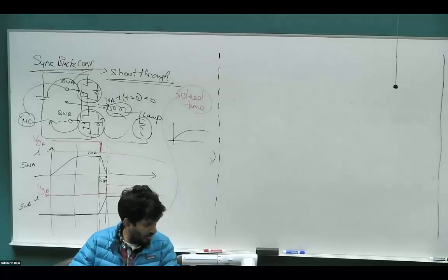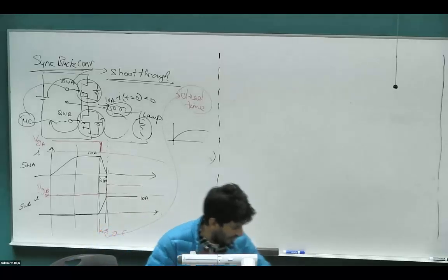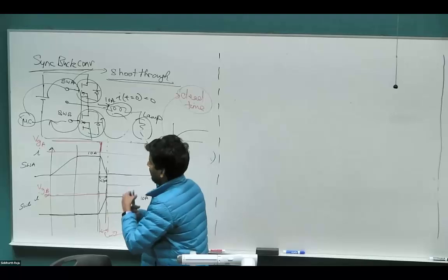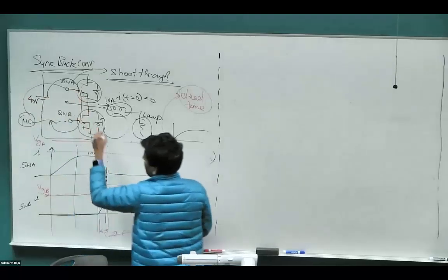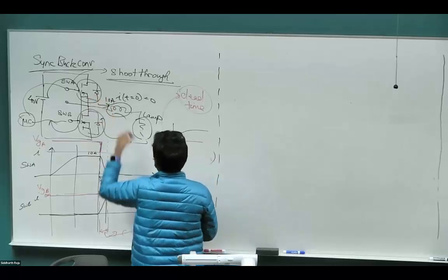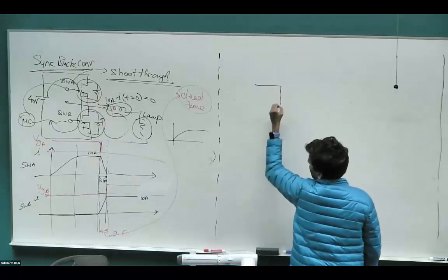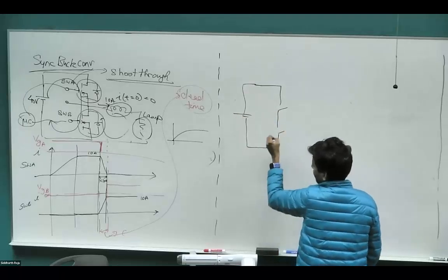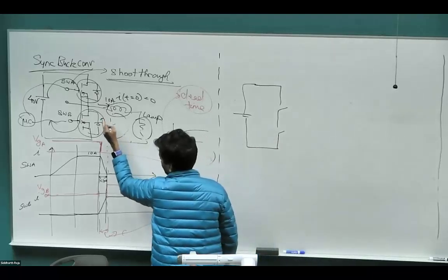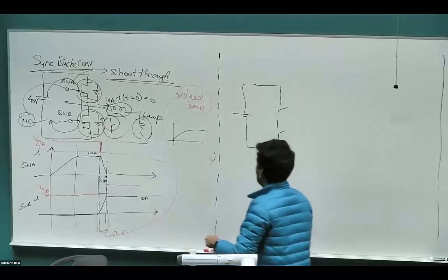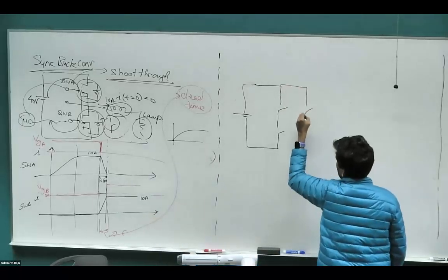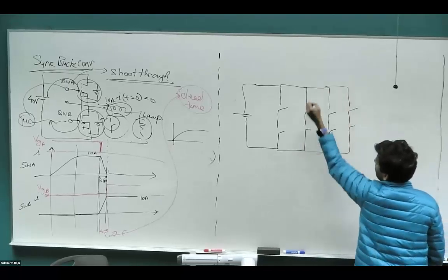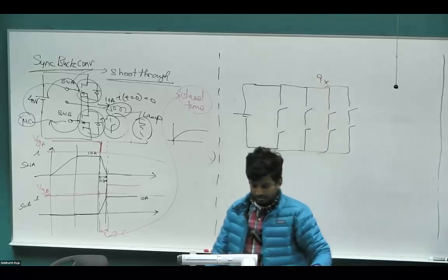Okay, so on the table again, I have the power supply, I have that black box. So now we know exactly what's inside the black box. It's basically just this DC bus voltage, which is 40 volts, connected to these two switches. And I can keep on adding more and more of these. Right now, we looked at only one. So instead of that switch, let me draw it like this, just to make it simple. Going forward, I'm going to use this symbol, which means this whole MOSFET. Whenever I use the symbol, it means a switch and a body diode combined together. The box that you see in front of you has a whole bunch of these repeating sections, and it has 9 of them. Those are the 9 terminals that you see outside.